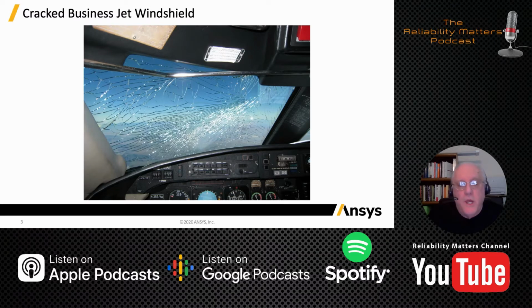So there's metallizations that allow the window to be heated. Typically, this would be on a small business jet, about 1 kilowatt per window. On the larger commercial jets, they're about 2 kilowatts per window. There's a sensing wire that runs around the periphery of the window. And the company that I worked for also made electronics, avionics for commercial and military applications.